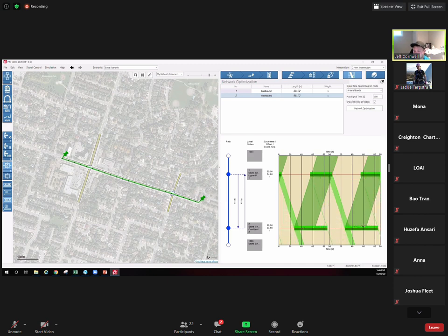And you can try different options here just by clicking and dragging. If I drag it this way, then this is probably about the best I can get that way. This would then be called simultaneous. Although these greens aren't 100%, because we do have more green time at Cortland than we do at Stone Church Upper Paradise, this would be considered a simultaneous progression because basically they're both green at the same time.